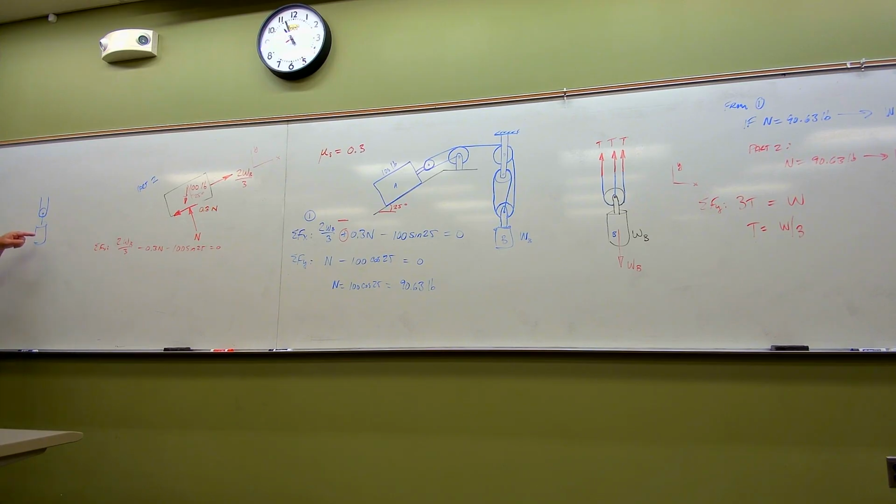In this case here, if you think about the weight force that's being applied to this, and the continuity of the cable, if we took little free body diagrams of the cable, whatever force is going this way in the cable would have to be the same as the force going that way in the cable. You pretty quickly can see that whatever force is in this cable here has got to be uniform throughout. In other words, whatever the force is here, it's got to be the same as the force here, same here, and so on and so forth, right? So in that case, if these are the same forces, then whatever this weight is, this would be half of it, this would be half of it, just equally distributed, right?